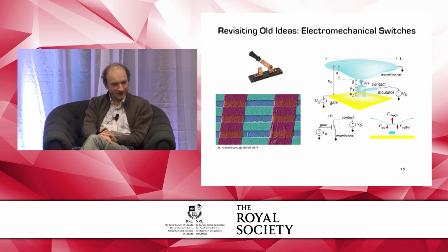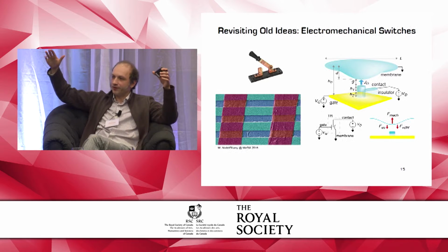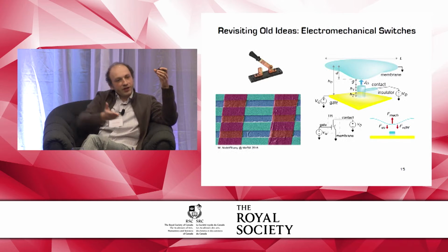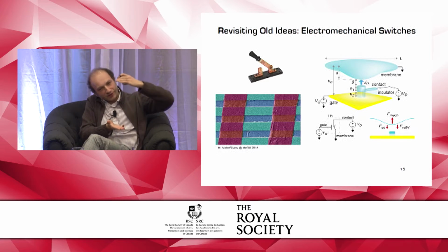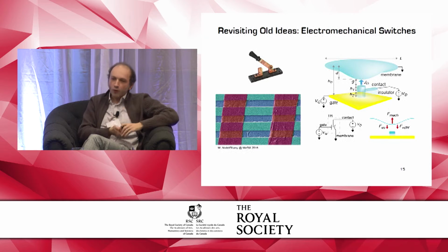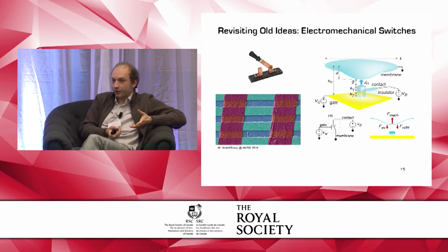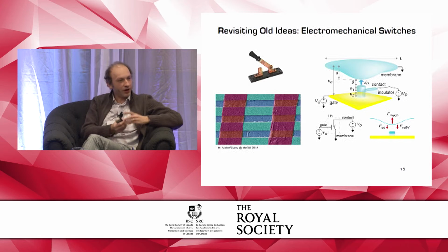And it's very difficult to see the shadow, perhaps. But these are a single layer of carbon atoms that are suspended above a trench. And it turns out that you can apply a voltage below and kind of get the graphene to deflect by some electrostatic attractive force and close the switch, then you can open the switch. And why not try to make the smallest switch possible? And can we make a reliable electromechanical switch, which is somehow going back on the history of computation, but on such a miniature scale that all the scaling of energy consumption is different from that which we know of now.